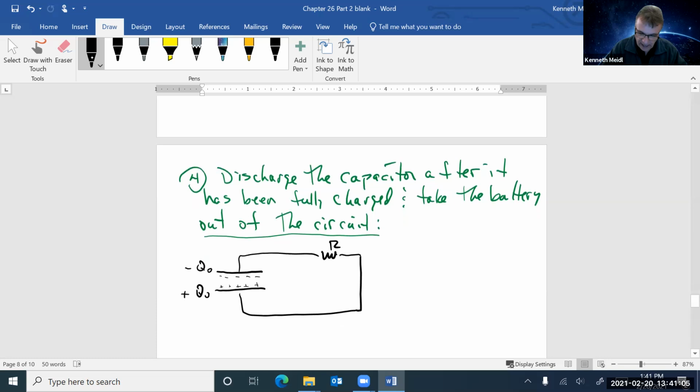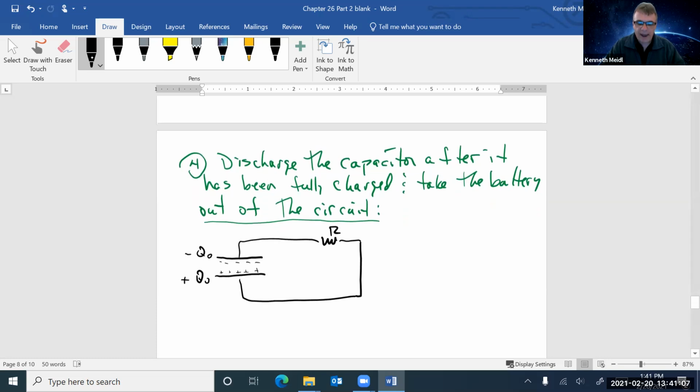And so, to work out any sort of mathematics here, always go to fundamentals. Usually you don't have to look any further for anything like that here at all. There are no junctions, and so really the only fundamental is to add up all your voltages and set them equal to 0. If I just circulate around this loop, I only have 2 elements here.